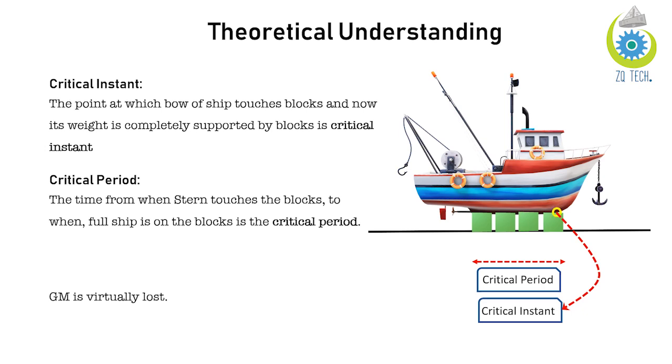Now move towards the definition of critical period. The time from when the stern touches the block to when the full ship is on the block is the critical period, as shown in the picture. So in this condition the weight of the ship will be equal to the thrust force.